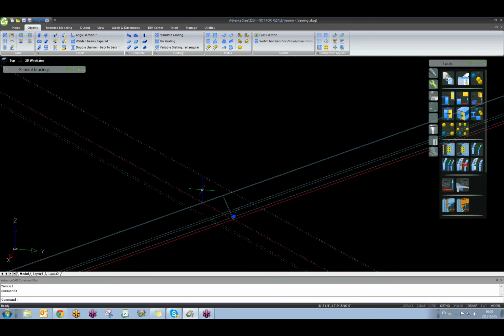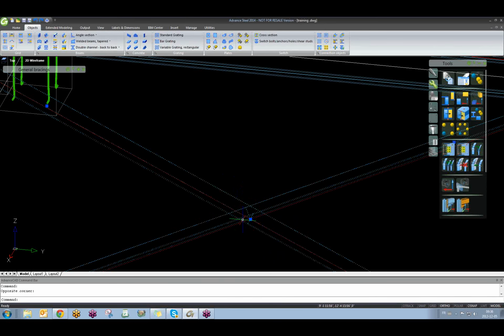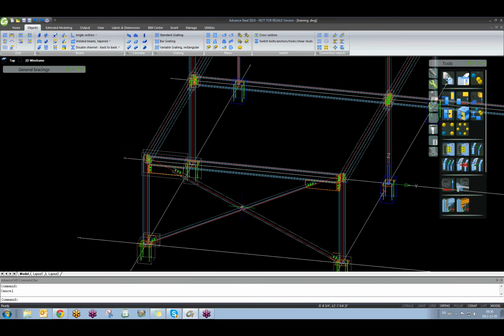I have to do that for this beam too. So if I go split beams, this one, enter, I'm gonna pick the midpoint, click, enter, and I will have 2 other profiles. Now I have 4 profiles in here. Seems to be good till now. The function split beams.